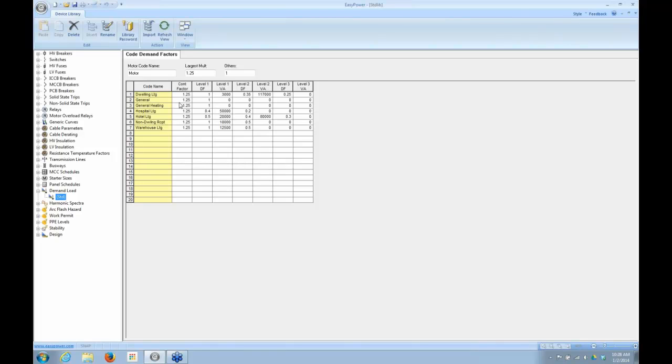So give you some flexibility here on how the loads get defined. We always have the motor category, so it's going to take 1.25 times the largest motor and 100% of all the other motors. And that can be adjusted here, but this would be per the NEC right now. Okay, so that table can be modified. You could add a different table, customized table, and reference that.